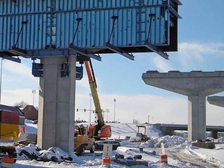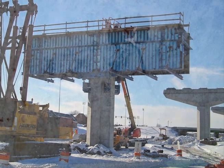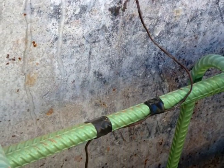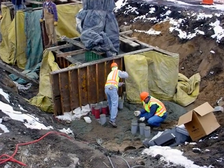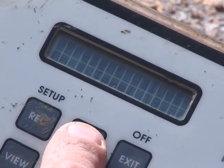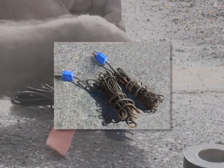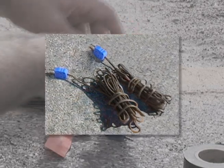The setup and monitoring procedures for structures are similar to those for slip-form paving operations. It is recommended using a minimum of 2 thermocouple wires placed in the structure, with a minimum concrete coverage of 2½ inches. The placement of the wires into the structure is at the discretion of the project engineer. Test the wires for conductivity by taking a temperature reading with a monitoring device. Once the wires are tested, it is recommended to take measures to protect the wires and connectors from being disturbed.